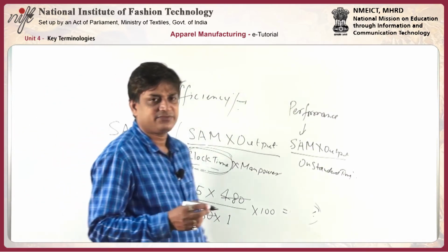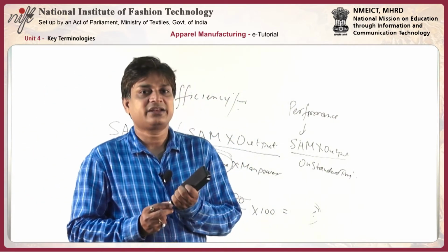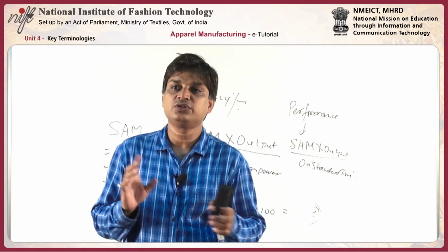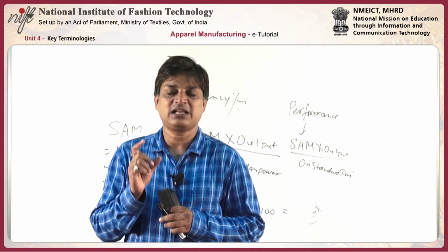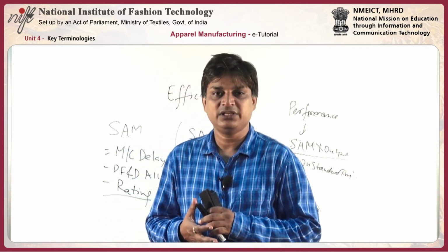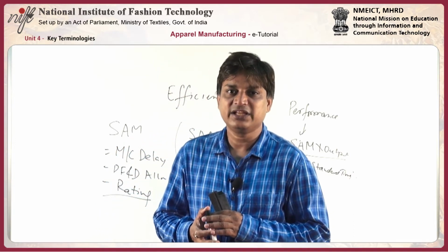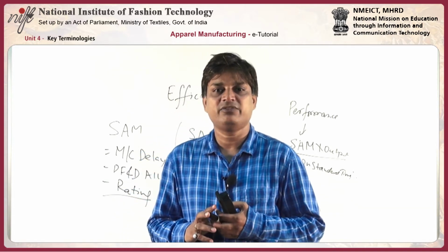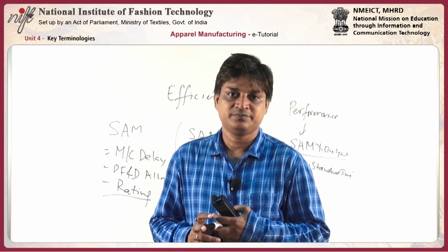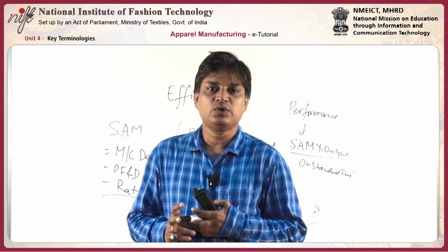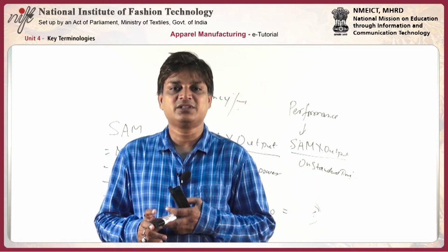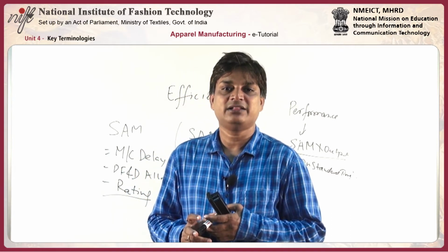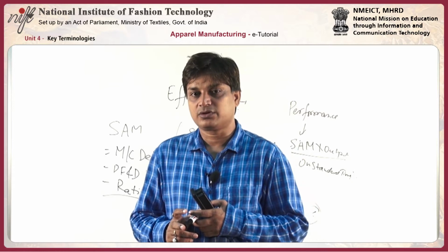So different allowances we talk about, and here the rating is a factor which is basically used during the time study. If you are doing the time study, the rating factor has to be taken care of. The rating corresponds to the average rate at which an operator will naturally work at a job, provided they adhere to the specified method and provided they are motivated to apply themselves to their work.